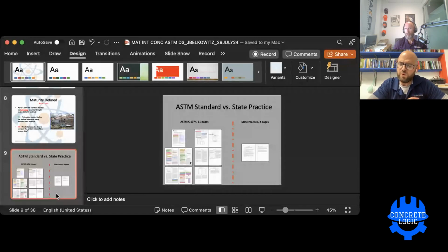The fastest way to tell if a ready mix provider has or has not done it the right way, and these are the ones to ask, is ask them for the datum temperature or the activation energy.